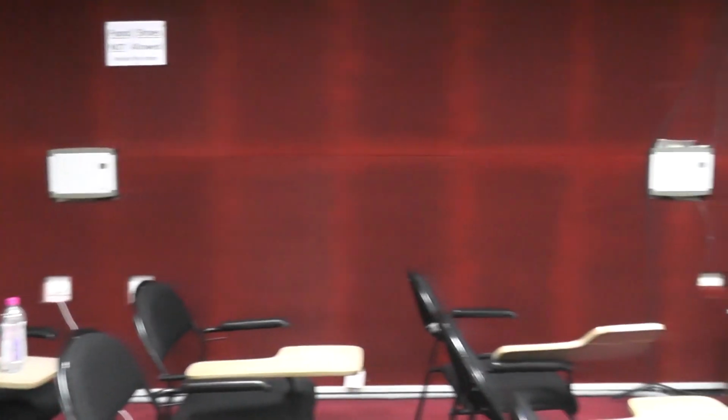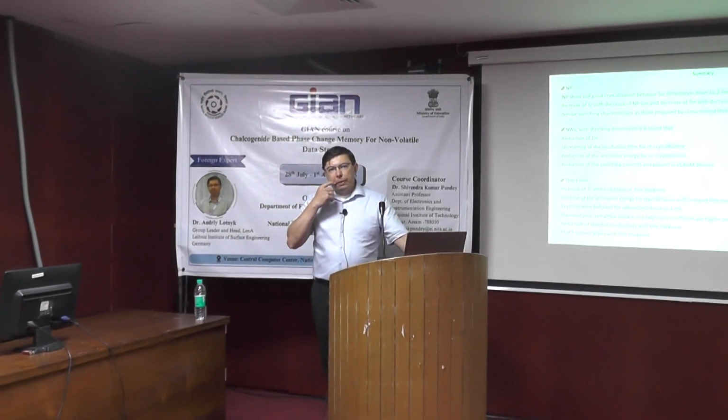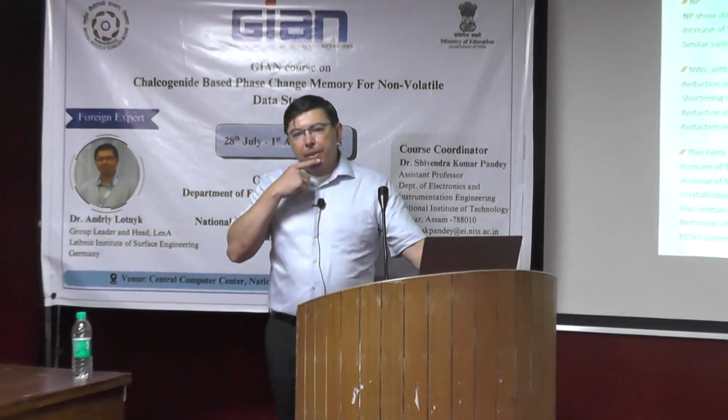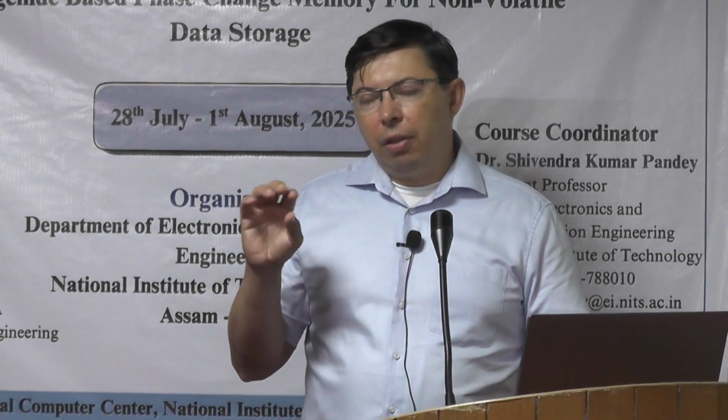Yeah, this is a very interesting question. I think there are not so many studies on that. There are some studies on the growth of very thin films of germanium telluride, and at a particular thickness, like less than 1 nanometer, they lose this metavalent bonding, and so they change the properties.